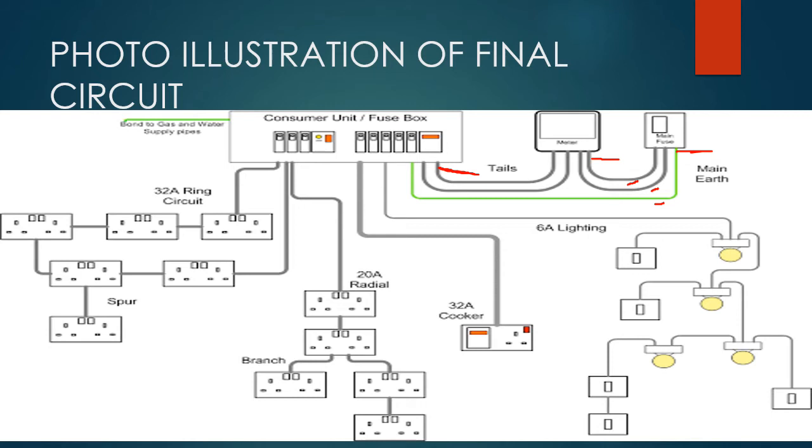So where you see a circuit breaker, that means that whole circuit is a final subsystem. I have told you we have a final sub-circuit for lighting. This is the one here. From the consumer control unit, we have the lighting sub-circuit that goes to the lighting, and from here we can see that we have various types of lighting.